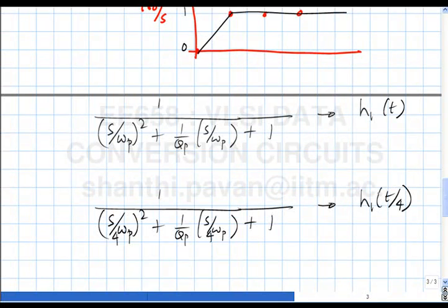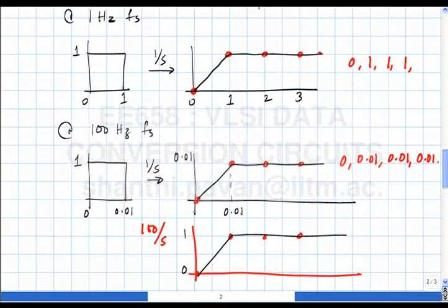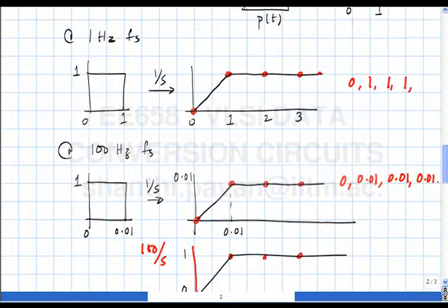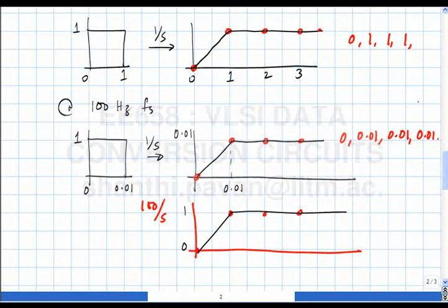Yes, sir. So suppose we have the ability to generate a pulse shape of 100 volts. Then doing that and keeping the loop gain the same as before, wouldn't that also work? Yeah, that will also work. Correct. So in this particular example, what he is pointing out is that instead of putting the gain of 100 in the integrator, you could have put the gain of 100 in the pulse shape. In this particular case, it definitely works, but you will see soon that in general it doesn't work at all. This first order example is one case where it doesn't matter whether you increase the pulse shape or the amplitude of the pulse shape or the gain of the integrator itself.